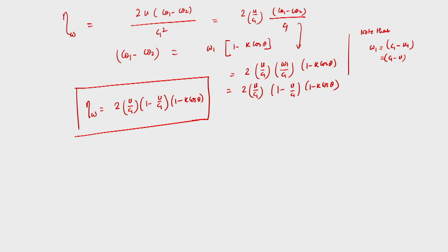So we may have a drop in efficiency. That is why the deflection angle theta is 165 degrees, the maximum deflection that can be done to obtain the maximum wheel efficiency. That can be obtained from this expression also.